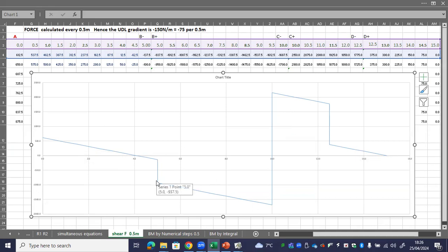These step changes here are the shear force of F1. Then we've got the reaction here, R2. Then we've got F2 coming down. And then the shear force diagram goes back to 0 as it must do. So how do we get the bending moment from this? We take the area under this curve, the area under the graph, and we can obviously see it's positive and negative.